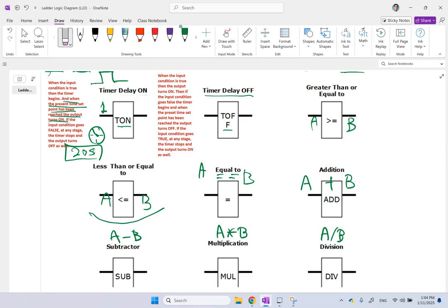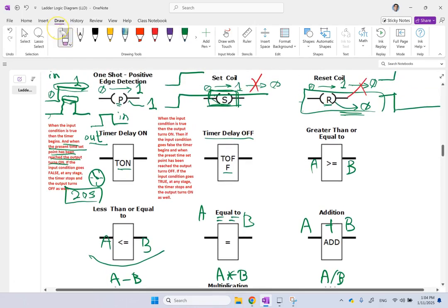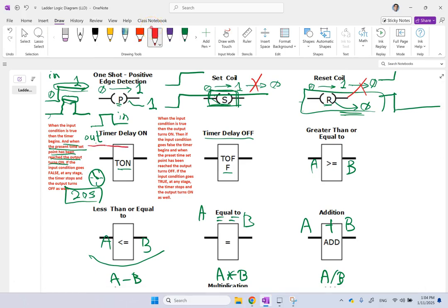So you see, it's not like, hey, I received an input pulse of 1, let me go ahead and turn the output on as well. No, it's not going to do that immediately. It's not going to do it right away. So if this is the input and this is the output, it is not going to go to 1 immediately like the input. It waits some time. So it waits after this some extra time, then it goes on. And this extra time from here to here, that is that 20 seconds of delay for turning it on.